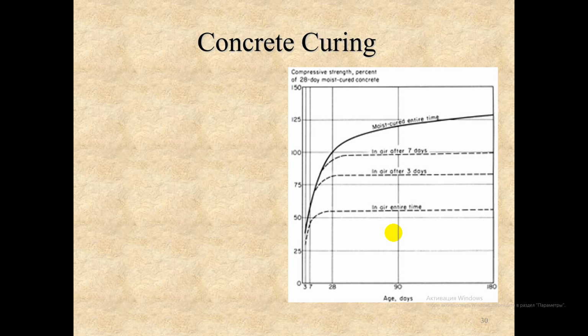Curing is a process which ensures the concrete has sufficient moisture to hydrate continuously, especially during the first week or so of a concrete's life, which is this critical period. Concrete can be gently sprayed with water, wrapped in damp hessian, or wrapped in polyethylene to prevent evaporation, or sprayed with a curing compound. This latter material again prevents evaporation from the concrete.